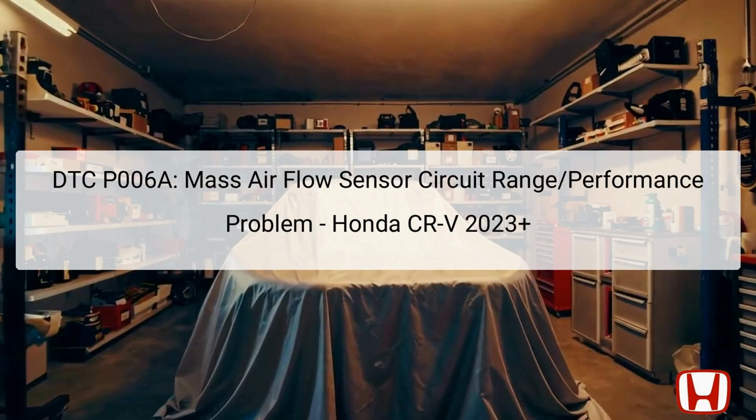and stores the DTC. The MAF sensor plays a critical role in measuring the air entering the engine, ensuring that the optimal air-fuel mixture is achieved for efficient combustion. The MAP sensor, on the other hand, measures the intake manifold pressure to assist in achieving the correct engine performance. Therefore, issues with these components can affect engine performance, emissions, and fuel economy.